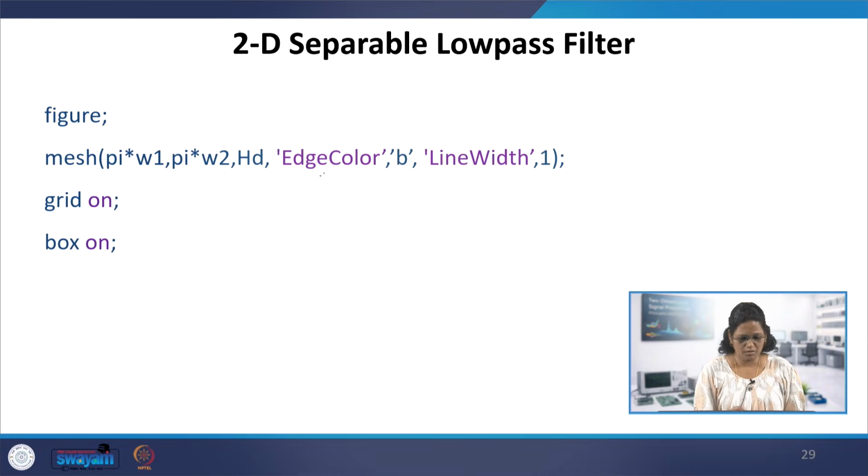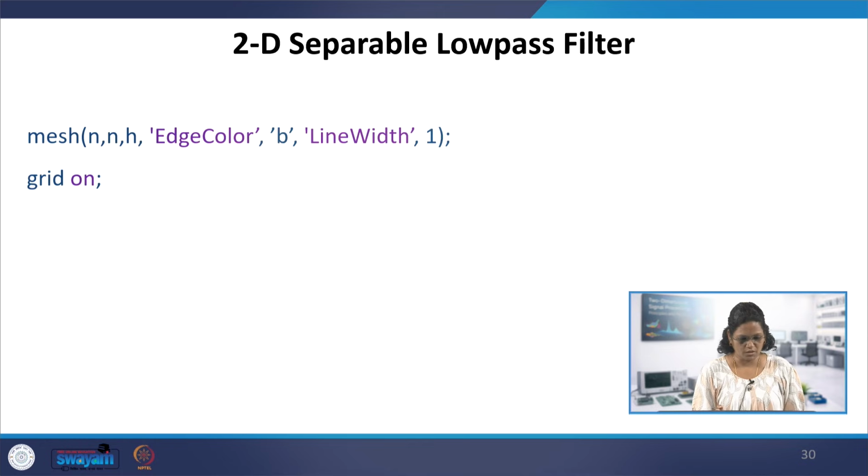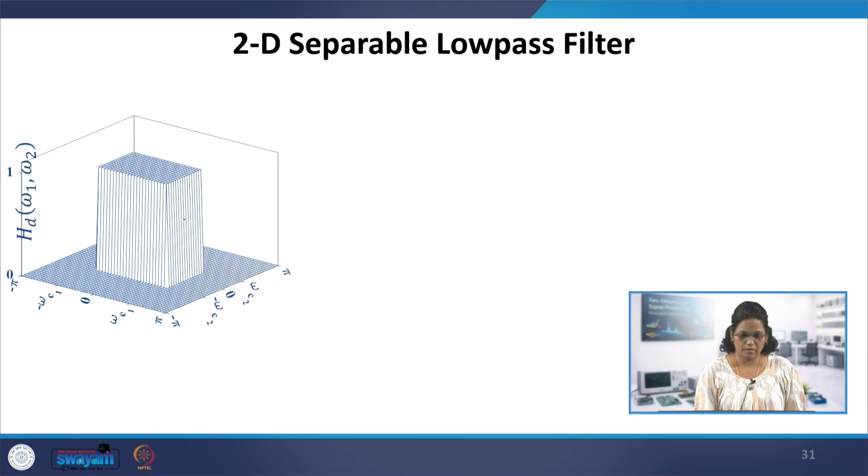So this part is just plotting. How do we plot the separable response and the frequency sampling filter as well? It's just some parameters used to plot. This is the frequency response of the separable case. Here omega C2 and omega C1 are defined, and this is the width and breadth of the filter, below which, where omega 1 is less than omega C1 and omega 2 is less than omega C2, all the values would be 0. This is only 1.